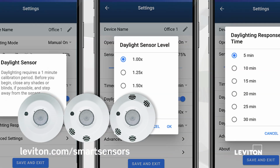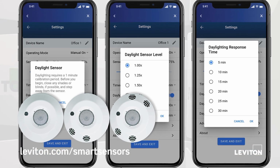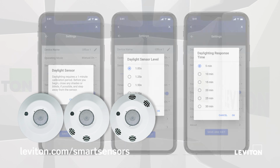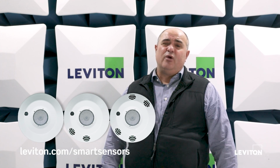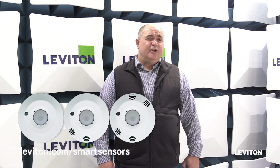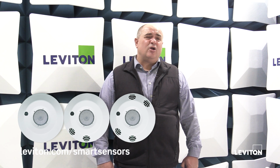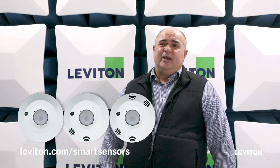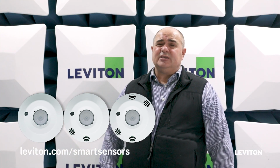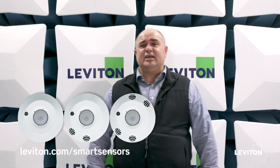And with regards to the daylight harvesting, that is something that often has to be fine-tuned along the way. It might not be right off the top. So to have the ability to fine-tune that from the app versus having to run up and down a ladder really is a very nice feature. And then of course the networking of the devices is a very key point. You don't necessarily want to have to walk from device to device, but to be able to do that all from the app itself is a nice feature. And then one of the nicest things that this app does is it not only allows you to set the sensitivities, but it does allow you to set scheduling.